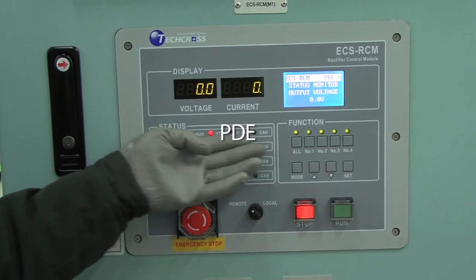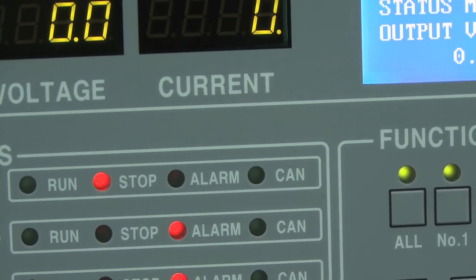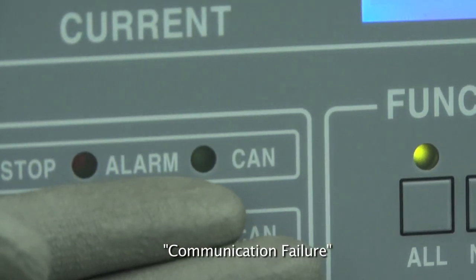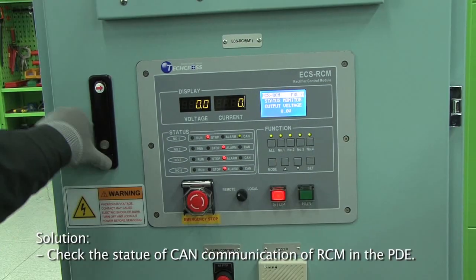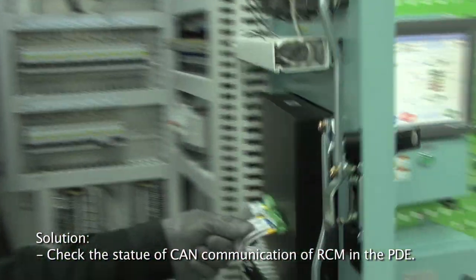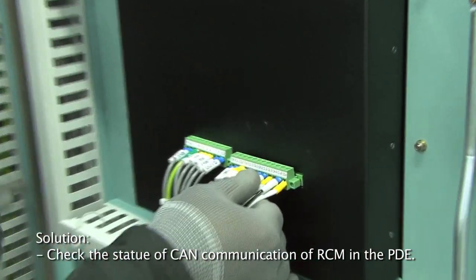2. Troubleshooting for each equipment. 1. PDE. Problem. ECS shuts down 1 minute after alarm message, communication failure, appears. Solution. Check the state of CAN communication of RCM in the PDE. Normal communication mode.